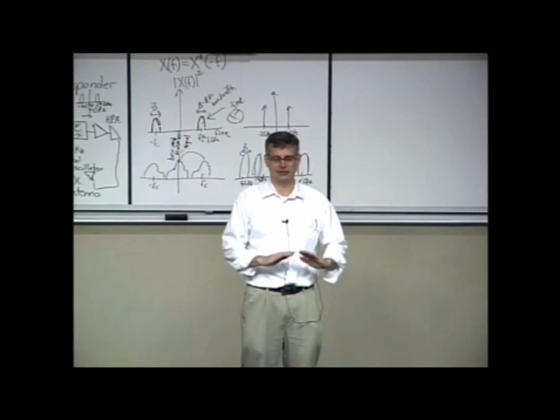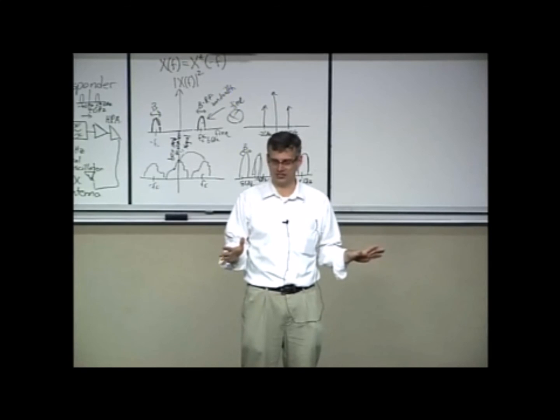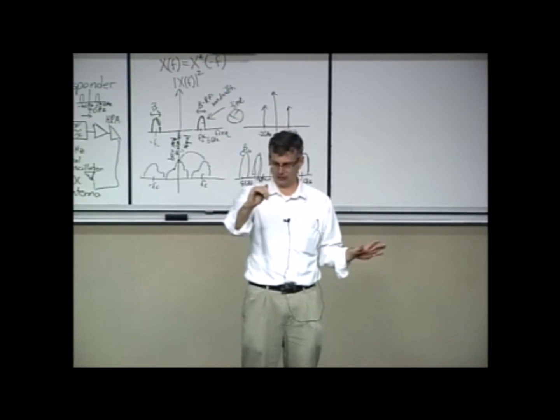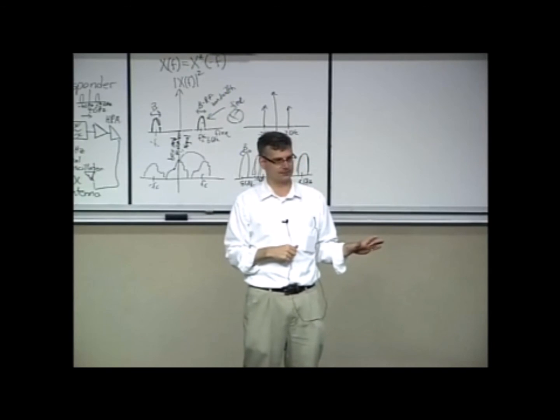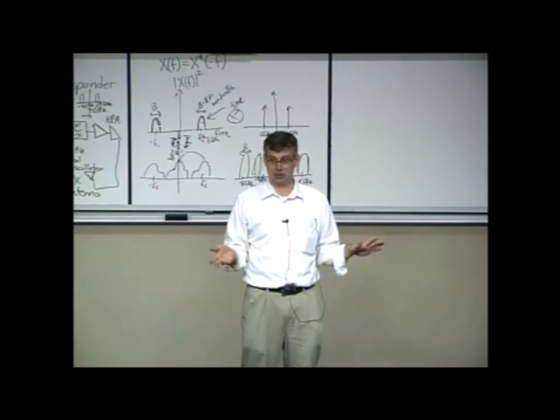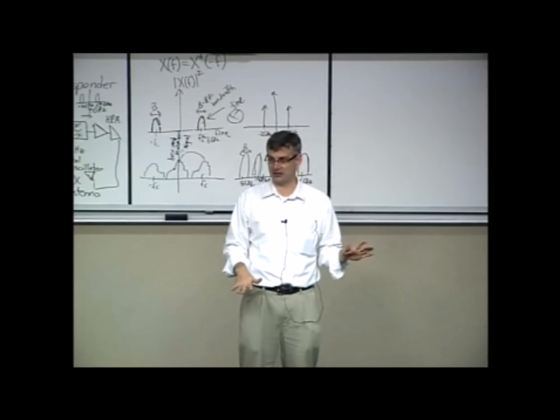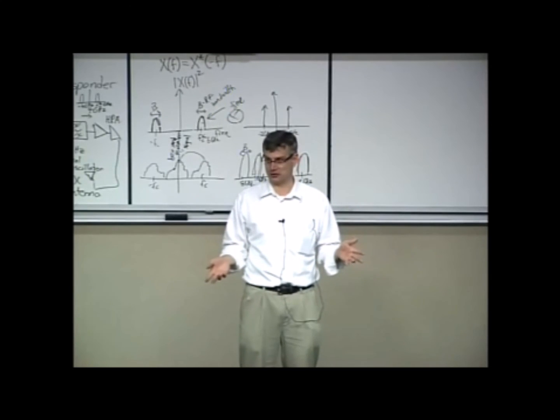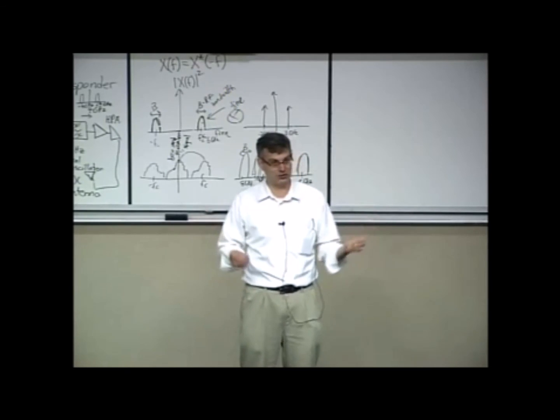Digital is completely the opposite. A well-engineered digital system will work perfectly down to a certain signal-to-noise ratio, and then it stops working altogether. But that signal-to-noise ratio is mercifully much lower than the analog signal needs for what is usually tolerable communications. This is why we use digital communications.